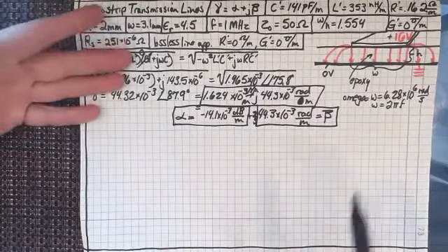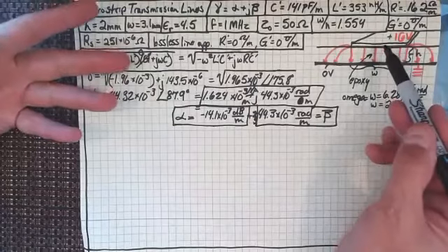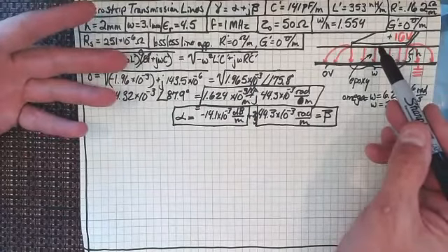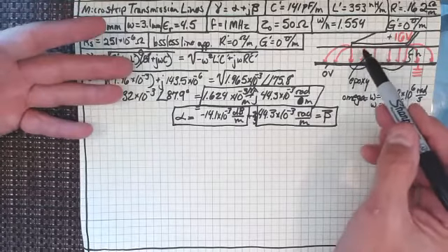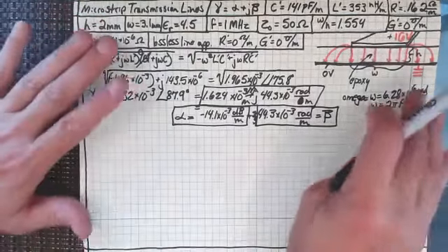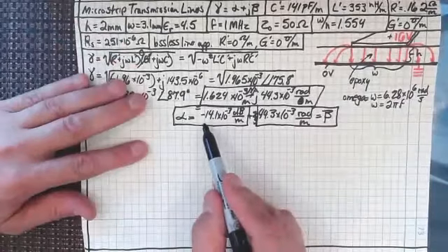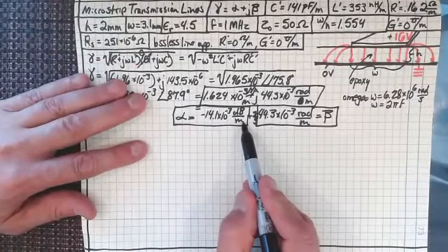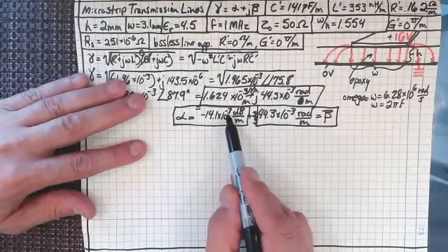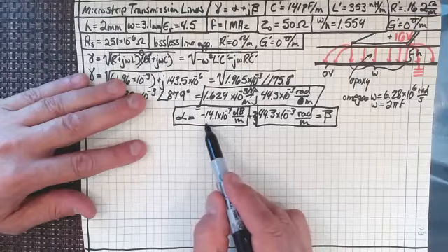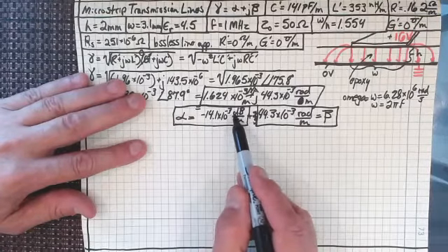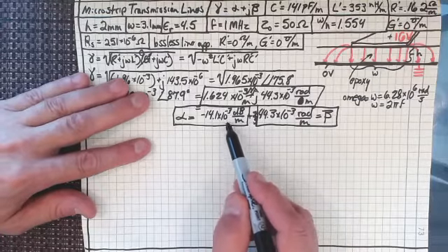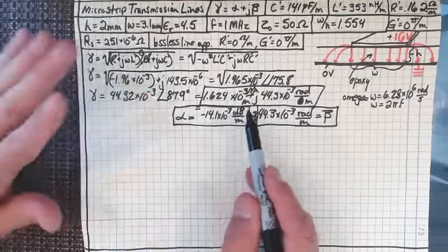But you've got to remember, inside your phone, how far is this trace really going? It's not going a meter. It's not even going probably 10 centimeters. So we don't really have to worry about this attenuation. Let's say I'm going 10 centimeters, or 1/10 of a meter. Then instead of being 14 millidecibels, it would be 1.4 millidecibels.